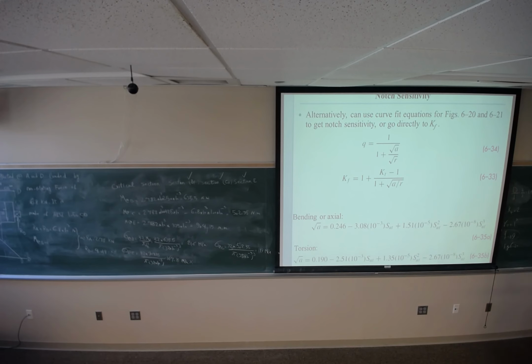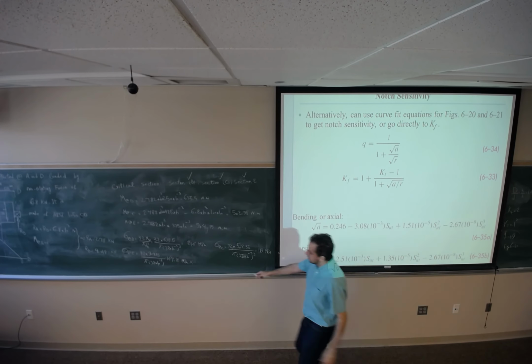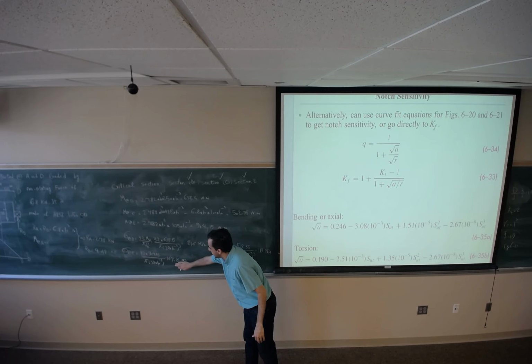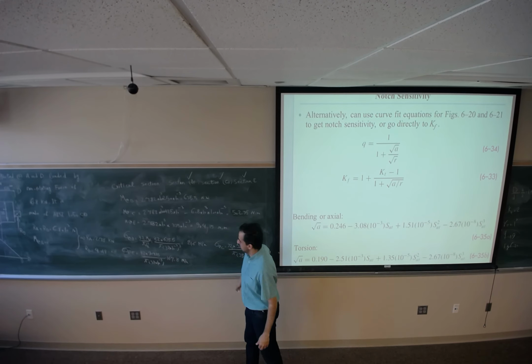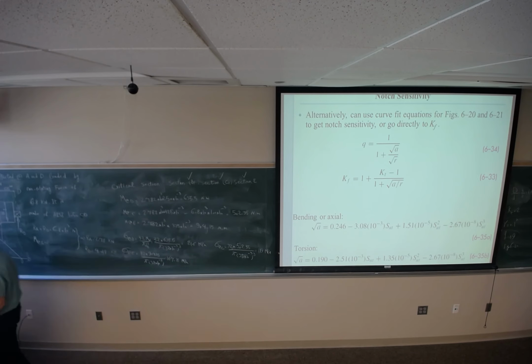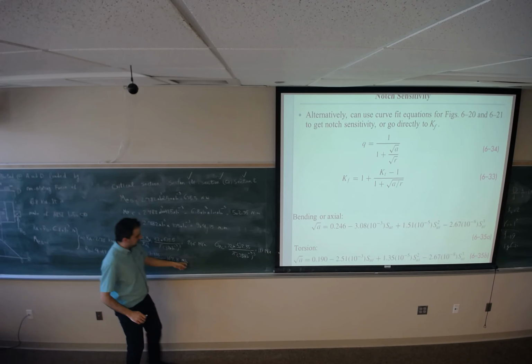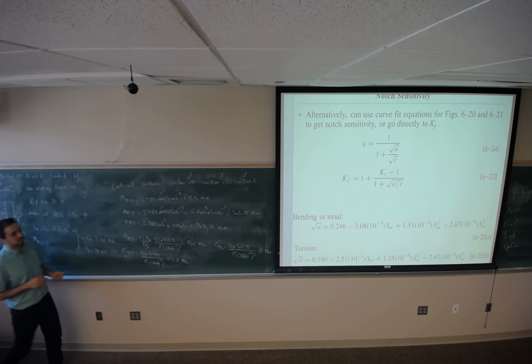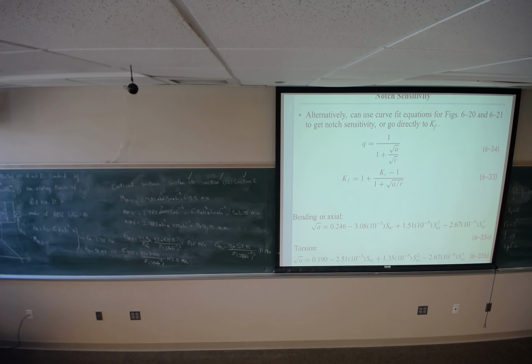But depending on the size, you might get a larger number for section E than the other ones, but you have to check the fatigue concentration factor to see what would be the greatest stress after considering the stress concentration. Any questions so far?